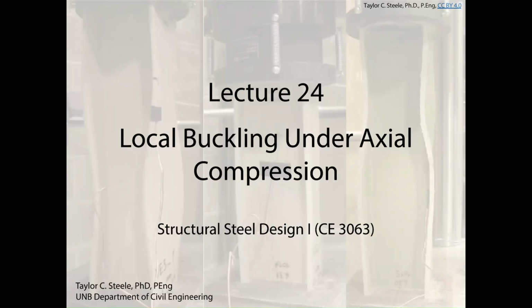What that means is today we're going to be talking about something called local buckling. So far, everybody should have a relatively solid understanding of what global buckling means: something buckling by bowing outwards along the full member length or twisting along the full member length. Today we're going to talk about situations where components of the elements actually buckle locally.